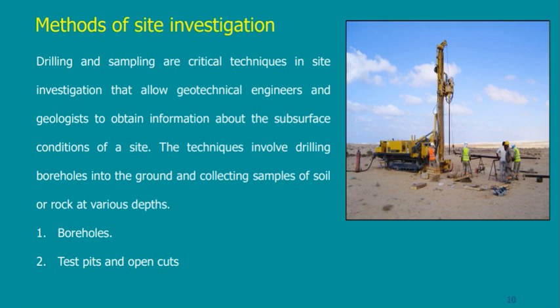I can use something instead of the boreholes called test pits or open cuts. Test pits mean in Arabic حفر مفتوحة, which means that I drill into the ground a hole. I go myself inside the hole, I see the sample with my eye, and I take the sample with my hand. So I can see it exactly as it is.